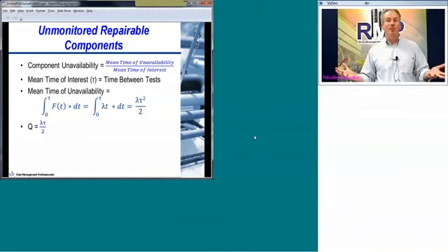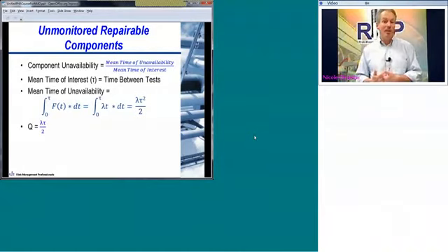Maybe it's a pressure regulating valve going to your flare off of some sort of head tank, and that never opens up because your tank is always slightly below its set pressure, and because it doesn't open up, you don't know if it's going to work. It's essentially unmonitored. A relief valve is essentially the same thing. It can be sitting there for years at a time without functioning, so unless you're pulling it off to test it, calibrate it, or replace it, you really don't know if it's functioning.